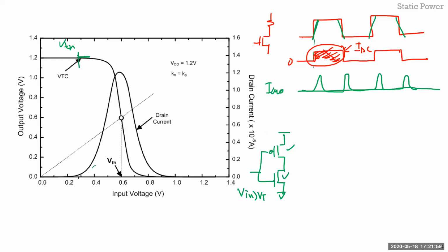So you're going to consume power, but it's very little power because your PMOS is a high value resistor right now. And then as soon as you keep going up and both of them are in saturation right at VTH, you have the maximum current flowing through this device, which depends on the W over L ratios. Unlike in the case of resistive loaded, it was VDD by RL plus RN.